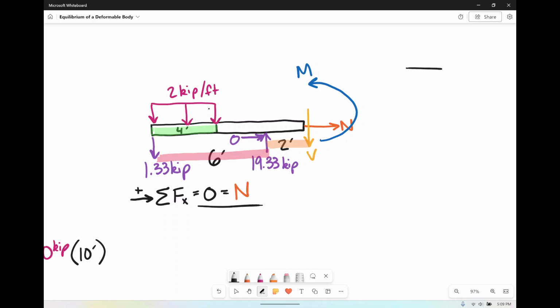So when we're looking at our answer blanks over here for normal, shear, and moment, if it was a value that wasn't 0 and it was positive, then you would say that that's in tension, and we'd put a little parenthesis with the T saying that it is going always out from the face. So pulling it in tension is a positive.